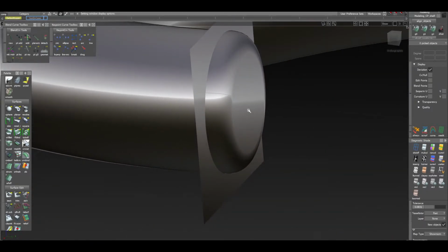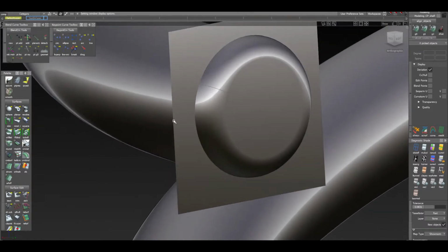Okay, so guys, the problem that we were having was that the fillet tool, probably the fillet tool, and the planar tool, between the two tools, we were getting curves on surfaces which were projecting onto the tubular offset, which was messing up our trim function, and things just weren't trimming properly. So what I did was I isolated the tubular offset object, untrimmed it, and took a look at the curves on surfaces. I deleted the curves on surfaces, and I recreated new curves on surfaces using the intersect tool with the untrimmed planar surface that we created.